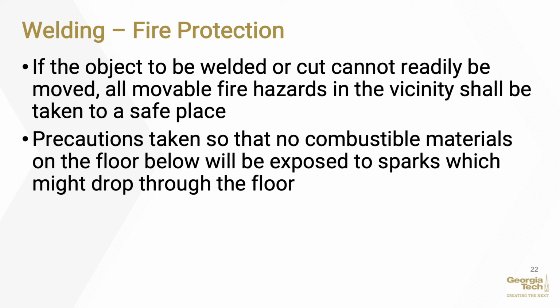Recognize and understand the job and the hazards of hot work, and follow safe work practices to prevent fires and explosions. If the object to be welded or cut cannot readily be moved, all movable fire hazards in the vicinity shall be taken to a safe place. Take precautions so that no combustible materials on the floor below will be exposed to sparks which might drop through the floor.